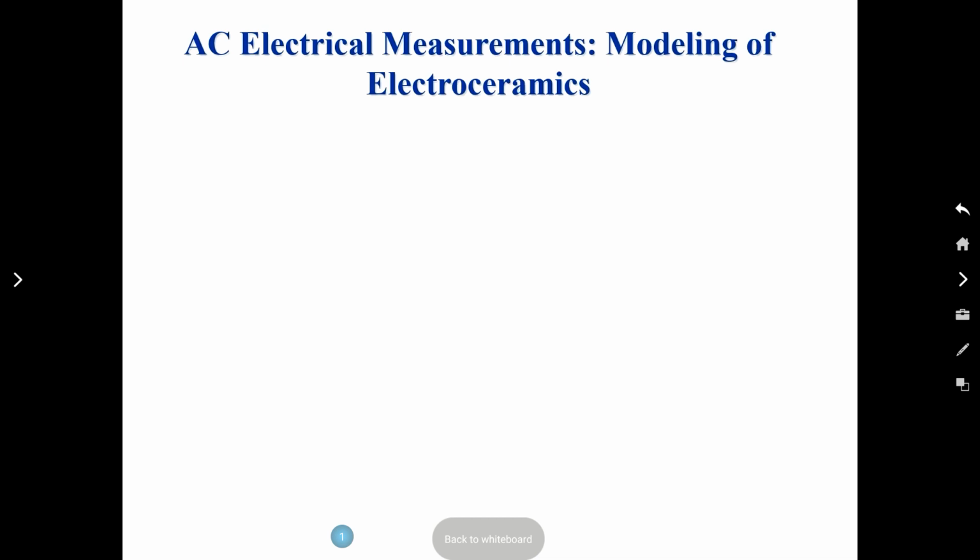Depending on the contribution of each, it will have an impact on the overall conductivity. So if you know how the grain boundary is contributing compared to the grain, you can choose to maximize the number of grain boundaries or minimize the number of grain boundaries. So that's the microstructural control.